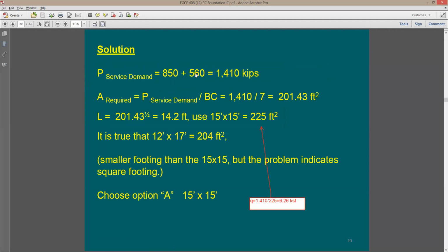Let's say 4,000 pounds per square foot. You have the total load, and the footing size may be given to you. So you can figure out the actual stress below the footing, compare it to the allowable stress, and be sure that it's okay. If it's okay, you say yes, it is safe. The stress below the footing based on the given surface load, when you compare to the allowable, is good.